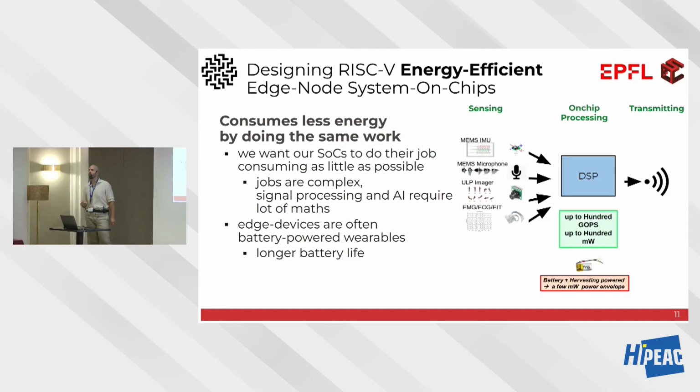Reducing the RAM movement. Yeah, so this is closer to, for example, the DRAM example. So you keep data closer to the processing element, so it travels less on the wires of your system. That means less switching activity on your capacitors, so less power.